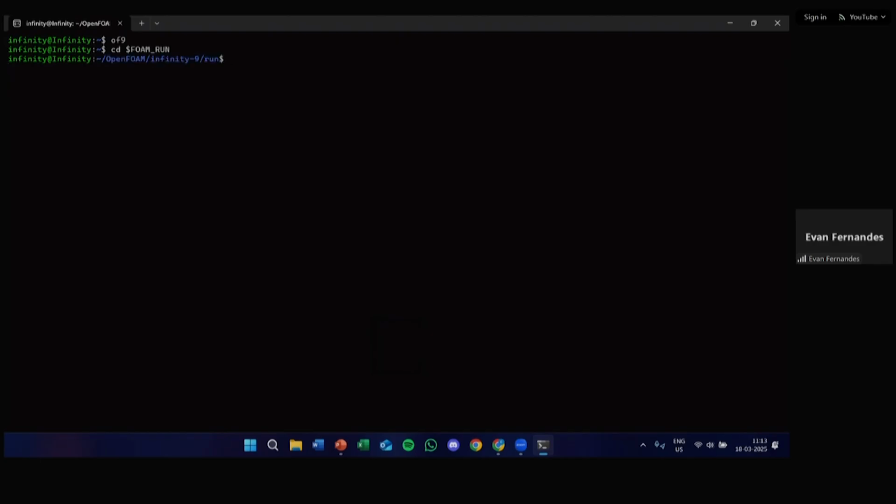Okay. So what this will do is it will take me to the run directory that we've created during installation. All of you must have created a run directory during your installation. So by typing cd $FOAM_RUN, you're going to enter that run directory. Has everyone done this?